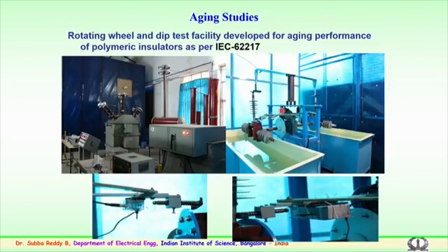When the insulator comes in contact with the high voltage, we have made a provision in the arrangement. You can see here the spring loaded mechanism. This gets in contact with the insulator, and you have a small shunt with protective arrangements. Further, this is taken through a cable connection to the measuring oscilloscope or the measuring device where we can measure the leakage current.